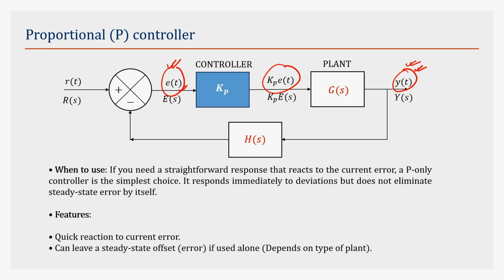Now, the problem with this type of controller is that it might have steady state error. We have seen that. Remember the example of 1 by (s plus 2)(s plus 4), that was the example we took where we had two specifications, 40% and 2 seconds. In that example, you saw that although we reached our desired objectives, we still had steady state error. The reason, we figured out, was that the type of the system was 0 to start off with, and for a type 0 system with unit step input there will be steady state error, and that is what we were seeing.